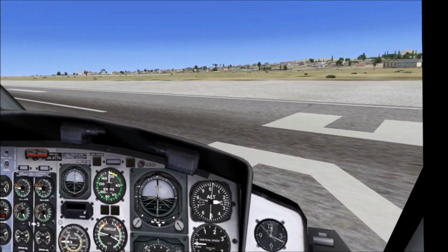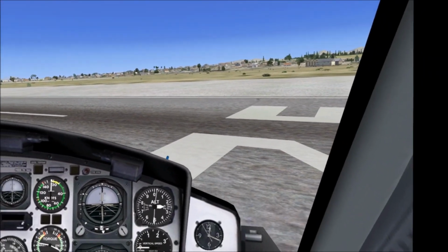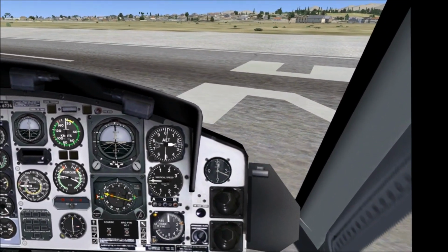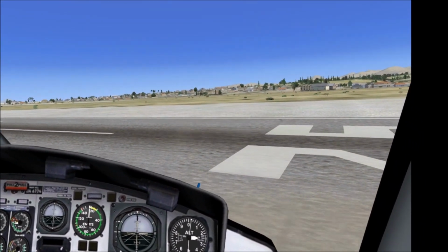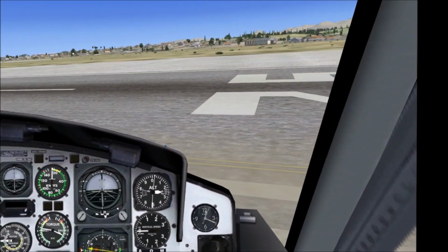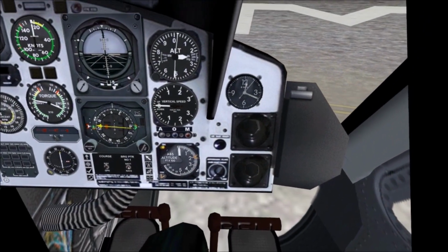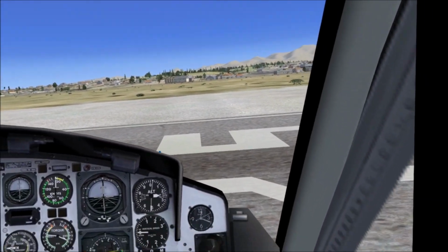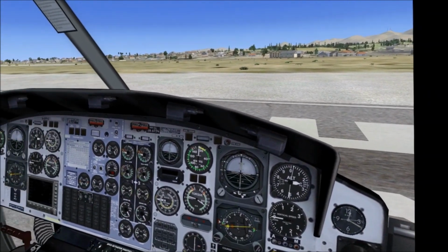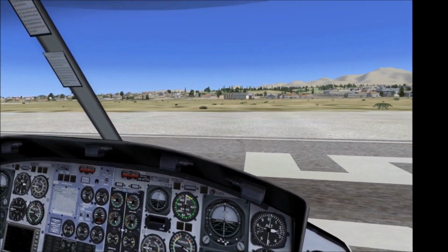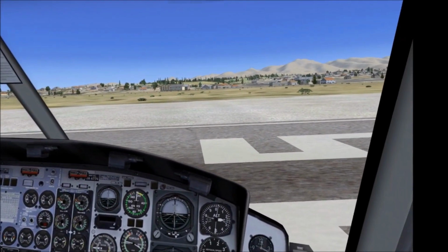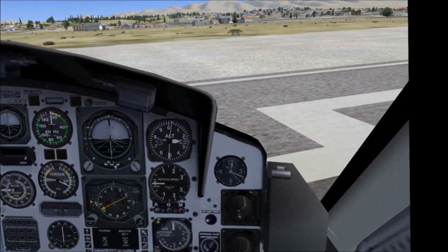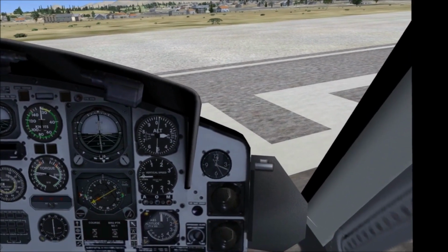I think I gave it a little bit more out of habit, as we did at 9,000 pounds. So I would expect a lot more this close to max gross weight than that sort of displacement. So I think it's pretty safe to say that that's not very realistic. I mean, no data or not. We just increased the weight by literally a ton, by 2,000 pounds, and very little extra pedal is needed.